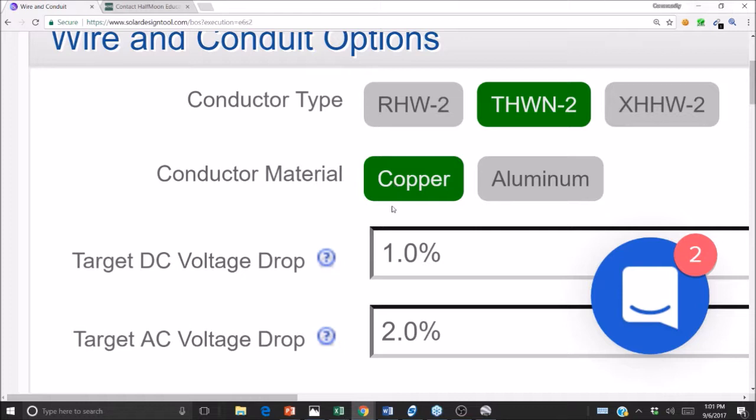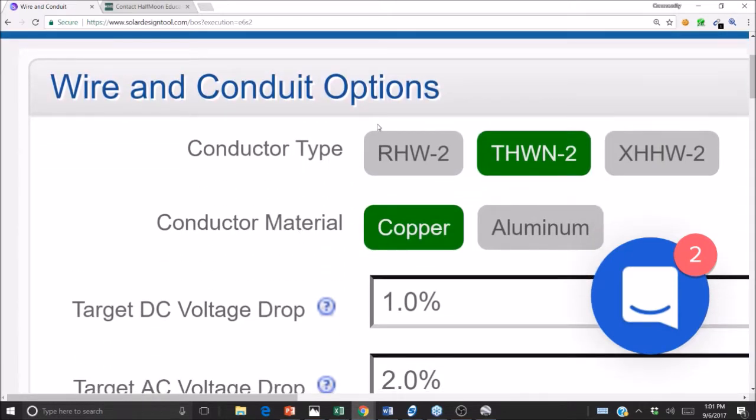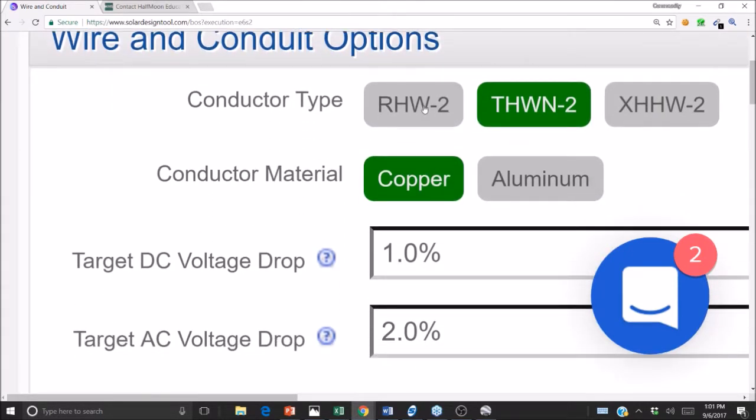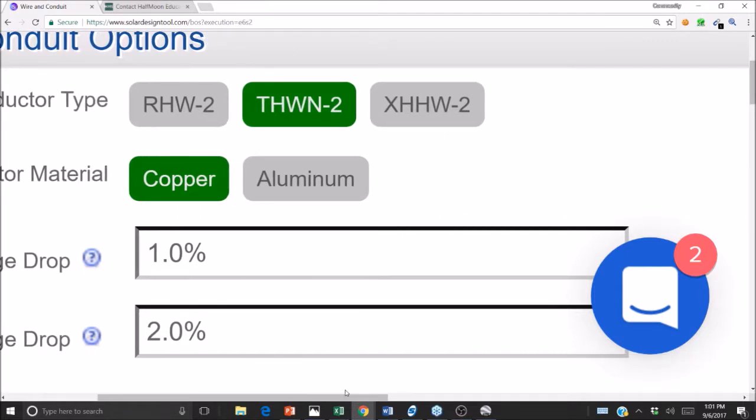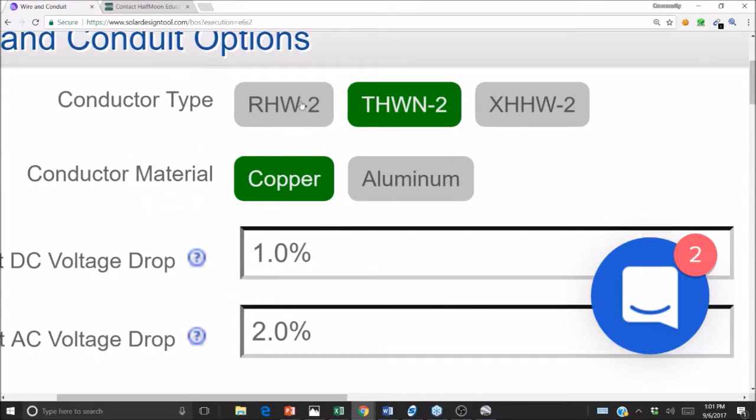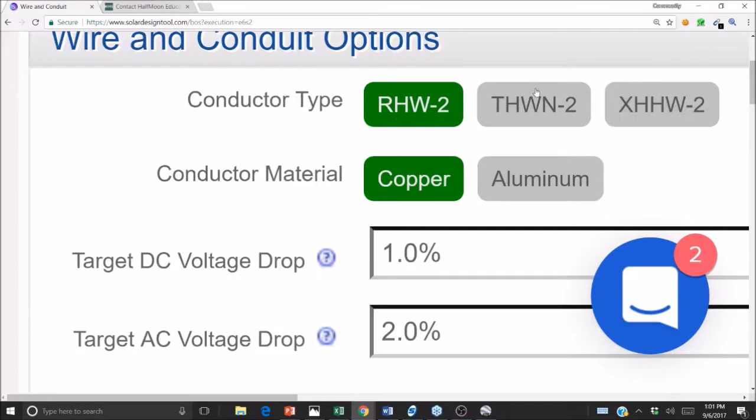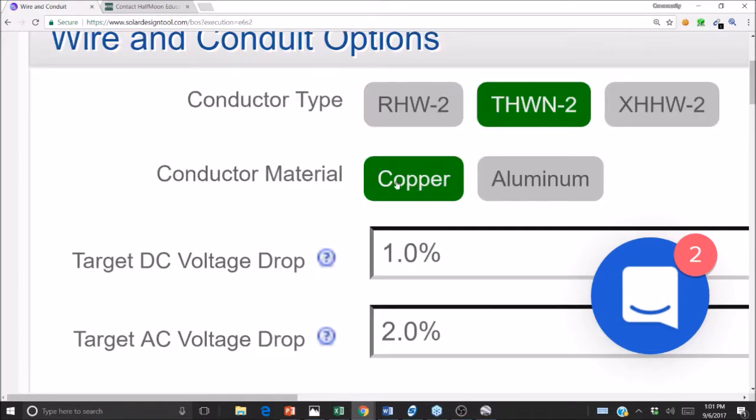In this particular solar design software, we see a survey asking which of these three cables you want to use. What this tells me is that if I have no clue what cable to select for my system, these are common cable types to select. What we'll learn later is that the W in these cable types refers to a wet condition, and the -2 refers to a sunlight resistant rating.